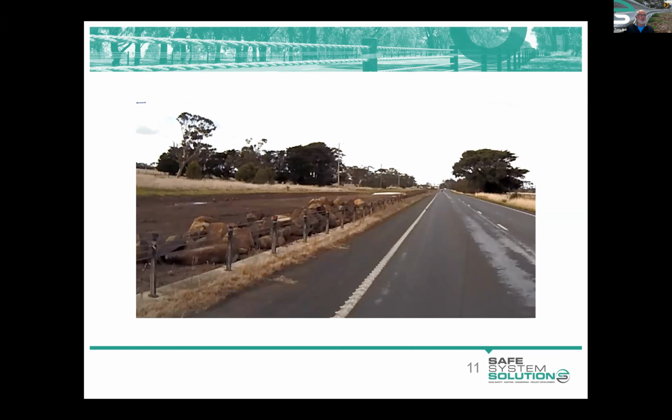If there was an errant vehicle, the deflection zone has now been filled up with a non-movable object, and therefore it becomes a hazard to the road user. So again, that wouldn't be picked up on a compliance audit, because it would be seen that, oh yes, the road is still able to be used for what it's intended. There's no interference for the through traffic, but there has been a hazard created because of the roadworks.